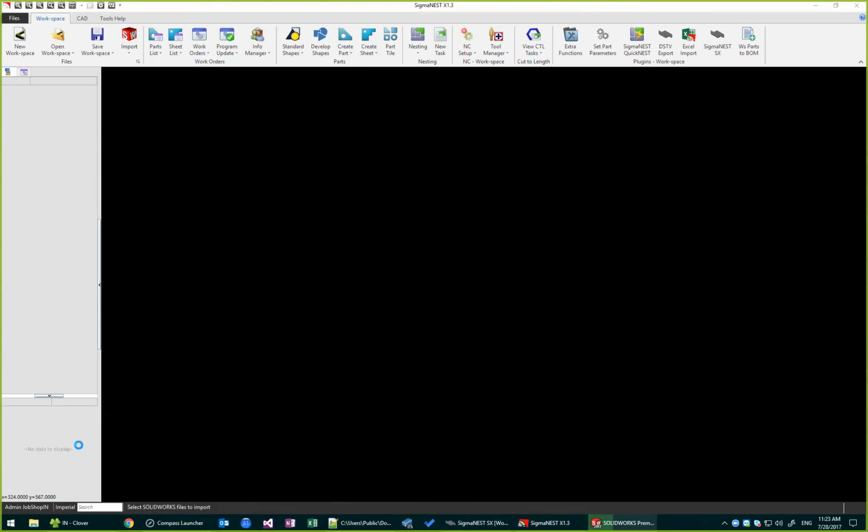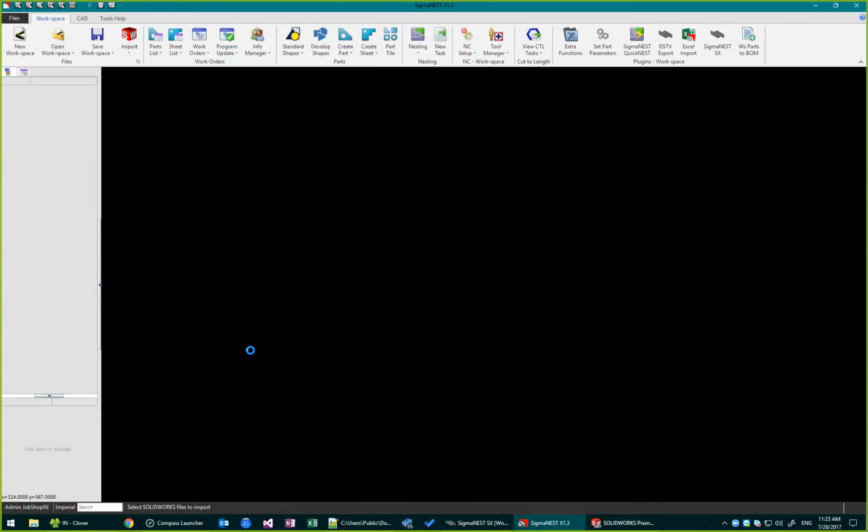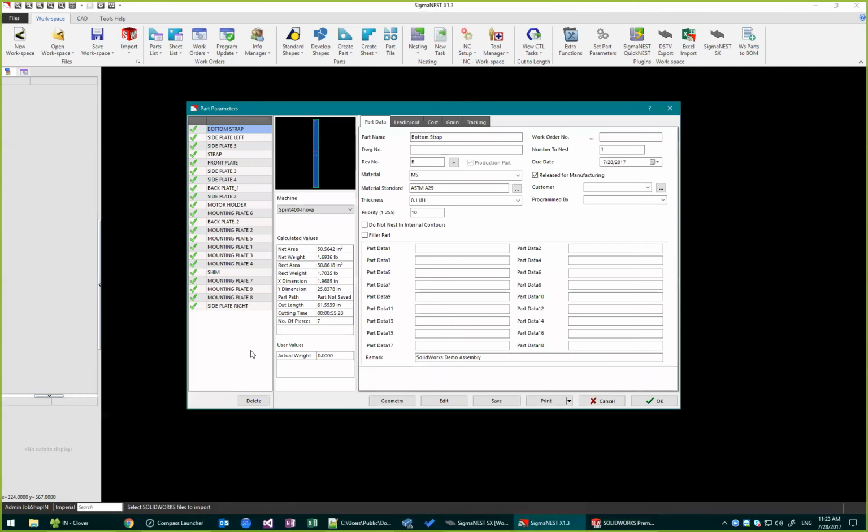Additionally, in that configuration, we had excluded some items by name. So we mentioned that if we name things with some intelligence or some convention, we can pick that up at the time of importing and just exclude them. And the other option that we had on, I'll cover this again once it completes and imports here, is creating a bill of material of this assembly, maintaining the quantities of each part.